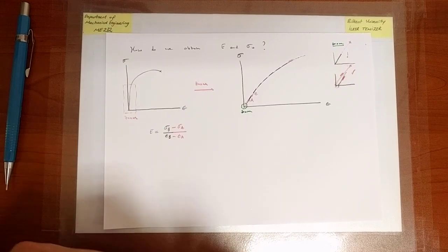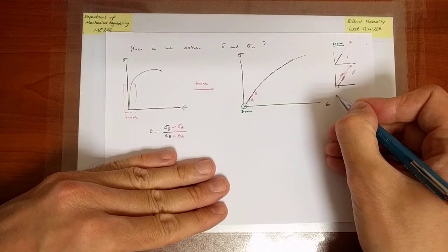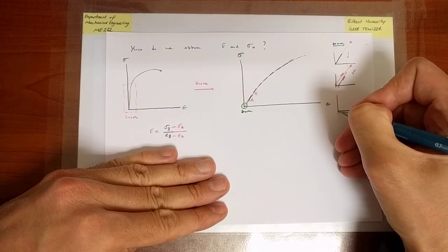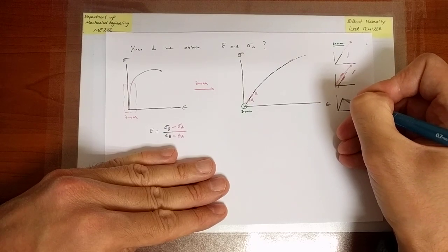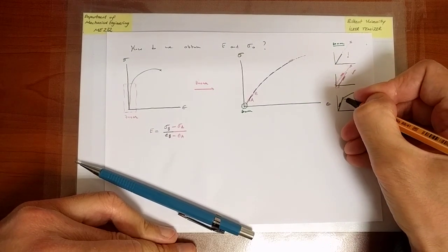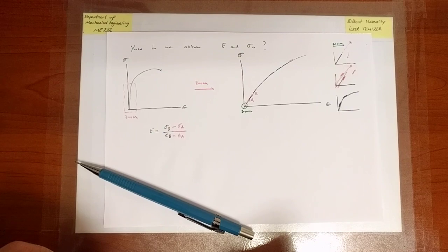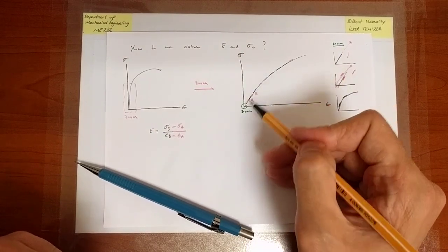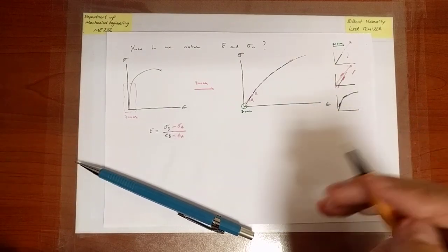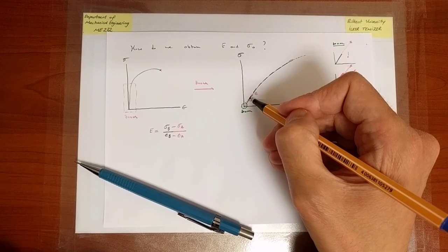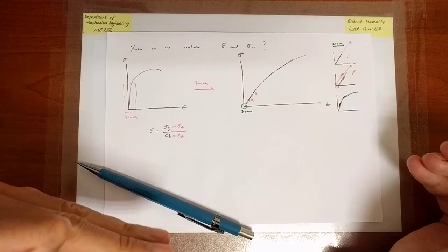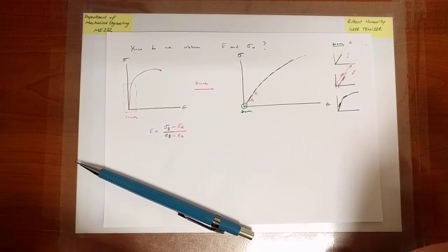Okay, now that's a good idea, but that simply goes back to our idealization. Our expectation is that the curve goes straight and then there is a distinct deviation in the slope. First it has a large slope, and then there is a certain point at which the slope all of a sudden decreases. This is not necessarily something that happens in reality, but that's certainly an idea we can build upon. Now perhaps another idea that has been expressed is that we keep monitoring the slope, and when the deviation in the slope is appreciable enough, then we say yielding has occurred.